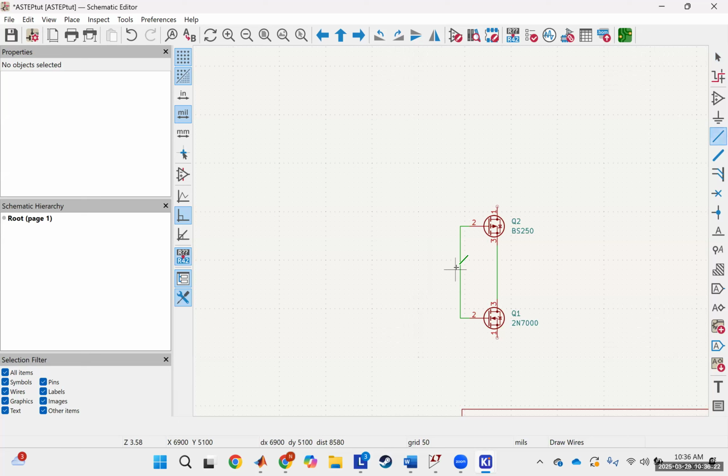And then I also like to draw little wires off the input and the output. So if you don't actually end on a wire, you'll have this thing where it keeps trying to make you draw a wire. So you'll want to hit escape. You'll want to double click actually. You want to come here and double click, and then that'll finish your wire. So you want to go to the other side, grab your output, and double click again. And then this will give you 2 little probes. We'll add some jumpers here later.